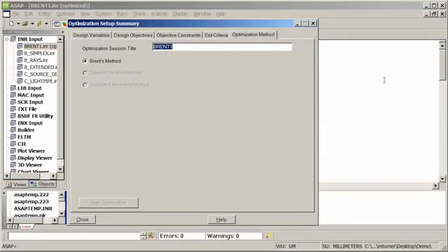These new tools are in addition to the optimization capabilities already within ASAP. In particular, we have added 3 new tools, one based on a Brent's method optimization technique. Brent's method is the tool that is appropriate if you have an optimization which only includes one single variable. Also available will be a downhill simplex method. The downhill simplex method is appropriate if you have multiple variables, but you have a relatively smooth solution space. Simulated annealing is available for, again, multiple variable optimization, but for those situations where you have a much more complex and possibly even discontinuous solution space.